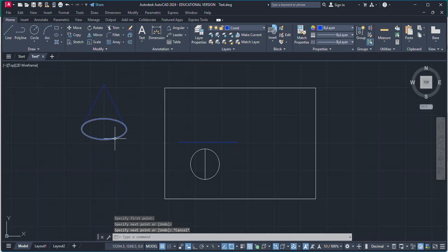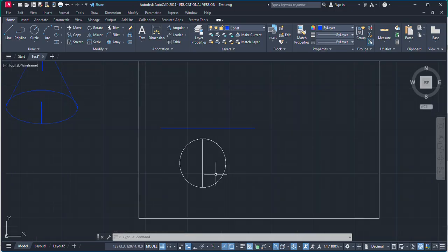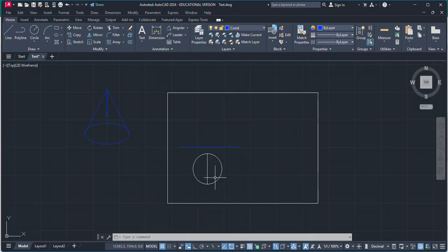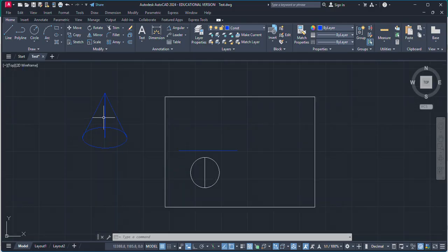Here, if it is resting on HP, then in the HP we will have the circle, which is 55 mm diameter, and you can see this top point will be there, as well as these slant edges. I've used here only 3 slant edges. So instead of these 3 edges, I'm going to divide this circle into 8 equal parts. Then we will have 8 equal slant edges.